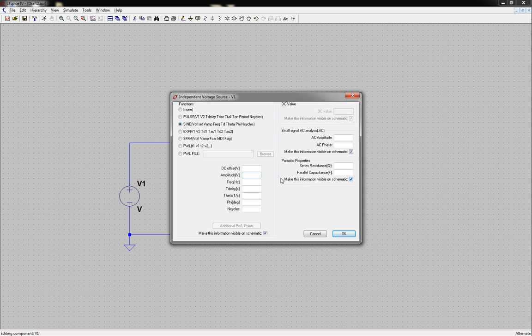I'm not going to go into why that is, because it's a long explanation, but that's what you have to do. So remember your square root of 2, and on 120 volt, if you take square root of 2 times 120, you get about 169.7, somewhere around in there. That's what you'll get for your peak value.